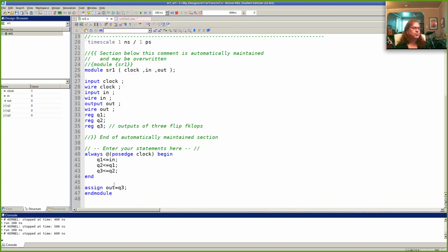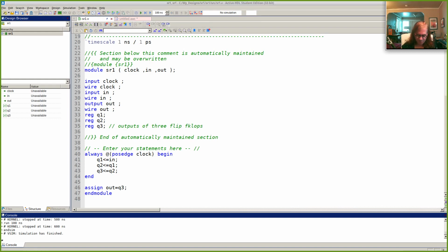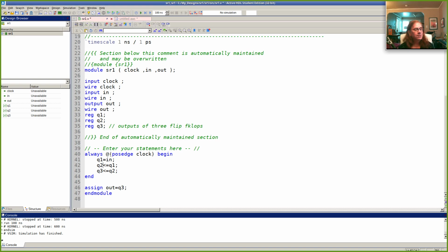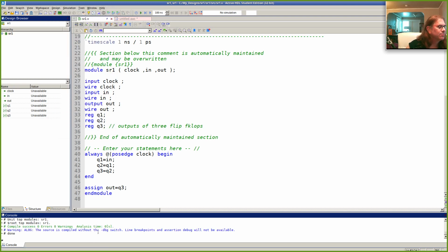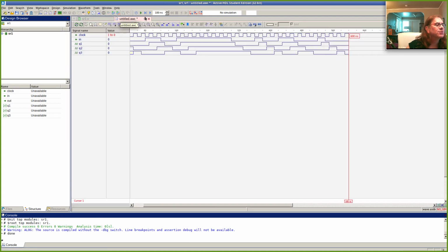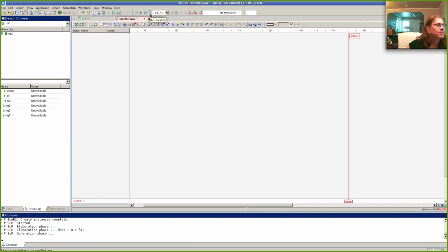So this is pretty simple Verilog code. But let me do one thing here. And I'll put a note here saying don't use a single equal sign. But let's take a look at what happens if we do that. So let's come over here, and let's forget that we were going to use less than equal. And so we'll take this and we'll compile it. And it compiles without warnings, without errors. So that's all promising. And let's go ahead and run our simulation.